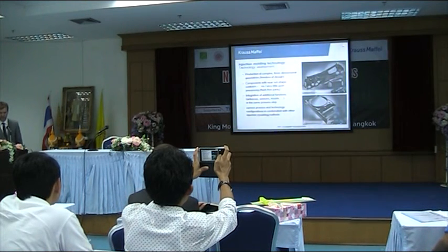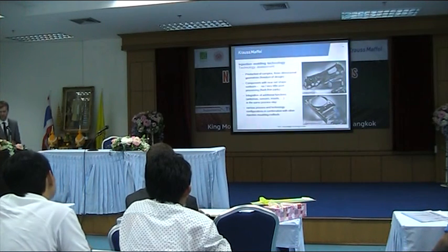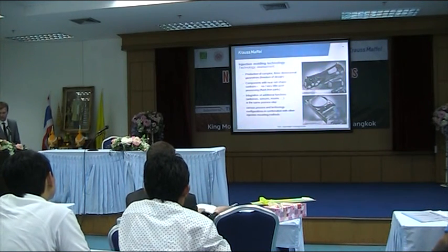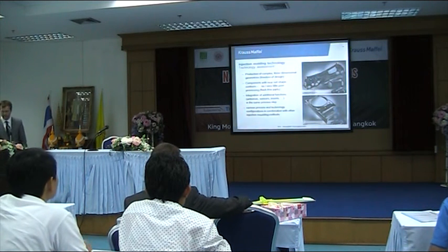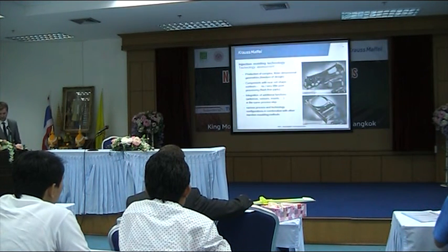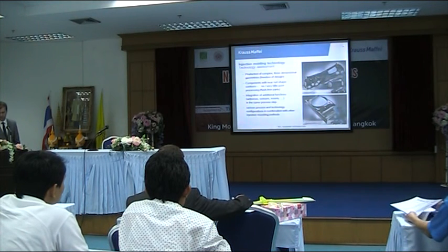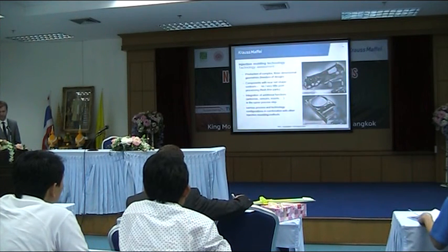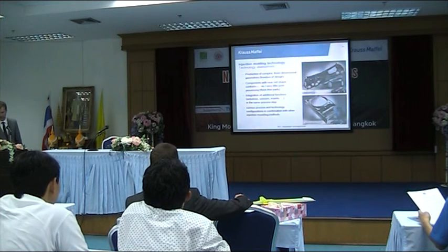And the production of very complex three-dimensional geometries is not possible. So it's this freedom of design which is a benefit, and components with near net-shaped contours do not need any post-processing, so you get flash-free parts, for example. This is almost never the case in treating thermosets.